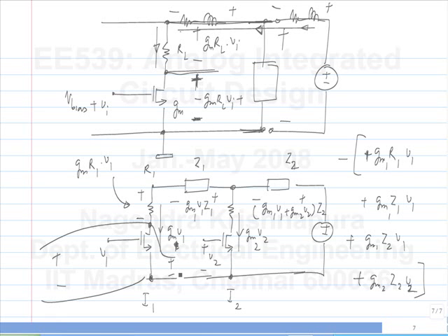So now the problem comes mainly because you don't know what the reference point for the signal is. In this case, you are getting GM1 R1 V1 across the resistor, but you are sensing the voltage between this point and ground. So the reference for the signal is not really used properly, or it's not known where it is. And because of impedances in the supply and ground lines, it's hard to find the exact reference point either. Now what happens in a fully differential circuit?